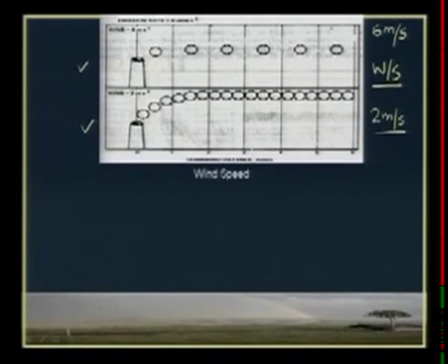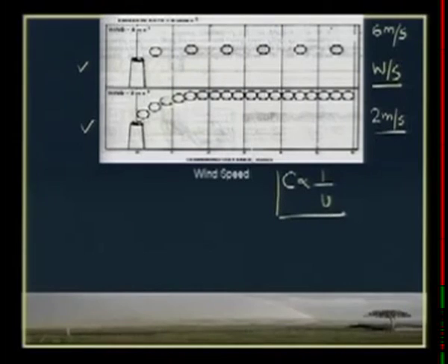You can see here the pollutants will travel fast, so the concentration will be smaller here, because you see there are 3 parcels of the pollutants still in this region, but because of the high wind speed pollutants are dispersing away and moving away. So there is only one parcel of equal mass. Normally we consider the concentration of the pollutant to be inversely proportional to the wind speed. That is a very important concept, and we will use it later in our succeeding lectures. So this is very important, that speed can directly cause a decrease in the concentration.